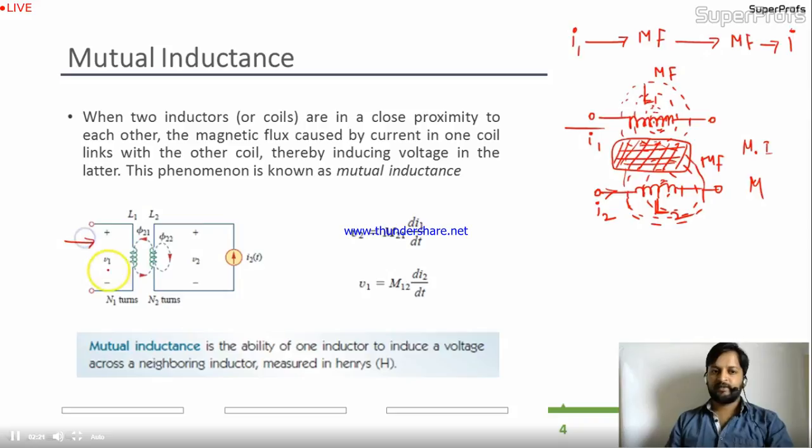See, this is the primary coil, the voltage is V1. This is the secondary coil, voltage is V2. In this, assume current I1; in this, assume current I2. I1 is flowing in this circuit and will drop some voltage over here, because you know the voltage in the inductor is L di by dt. Yes, it will drop something. But at the same time, it will get some voltage drop because of this I2. Remember, I2 is affecting the primary, and I1 is affecting the secondary because of the mutual inductance. So we have to write the parameter related to I2 also.